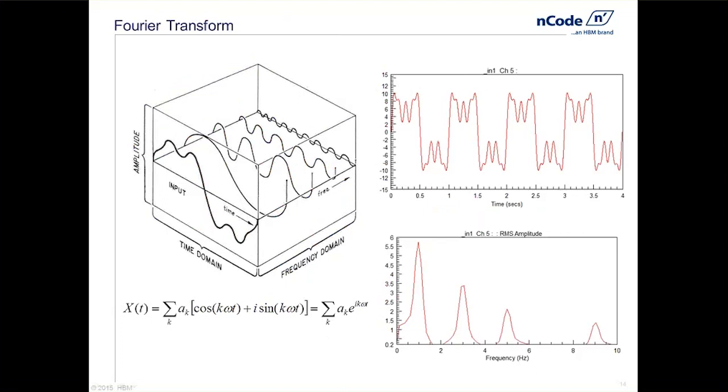We can see here the time series data. This is that original signal, a very simplified example. And if we looked at the frequency content, we could see that it is composed of 4 very prominent frequencies, and that would be these sine waves right here. So our PSDs are, in most cases, not quite like this.